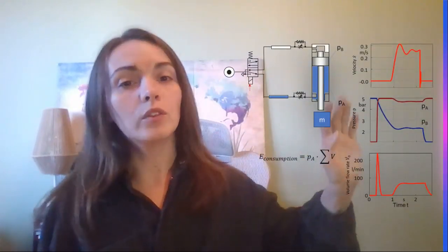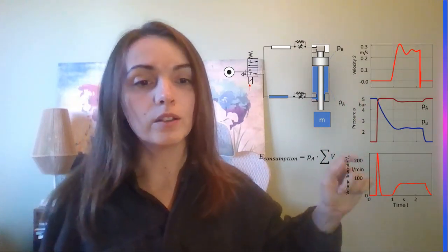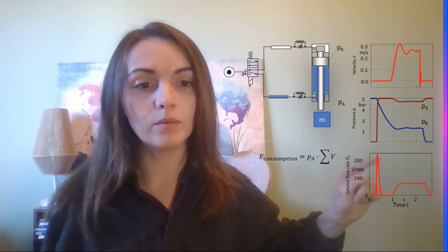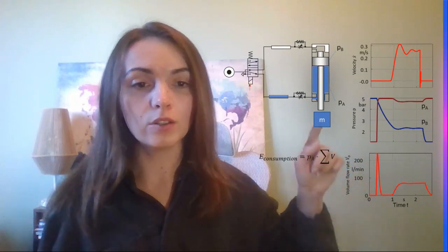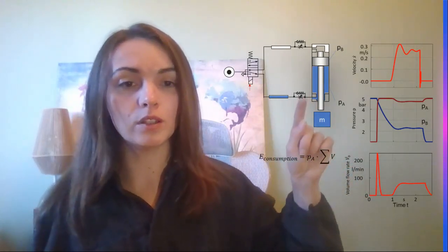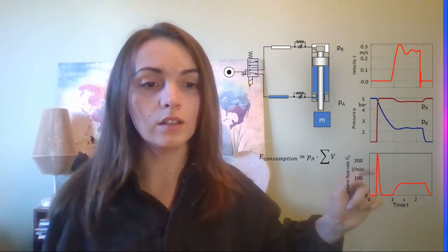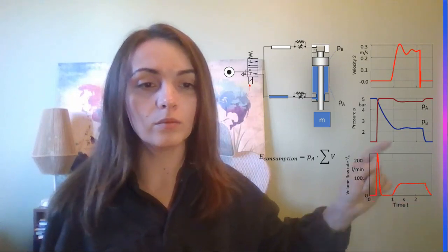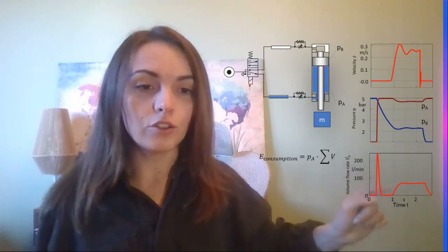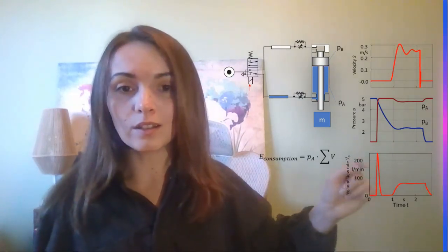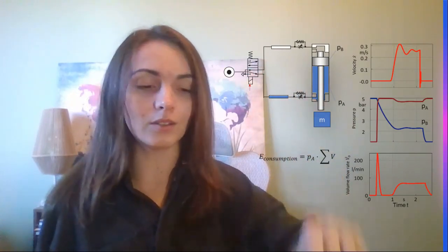If we look at the same velocity profiles, pressure profile and also volume profile, here you see this spike. It's basically the filling of the tube and dead volumes of the cylinder. And this part is basically the... this part. So what is happening when we actually need the stroke? Logically, we can see that to avoid these spikes, we need to locate this valve directly onto the cylinder.